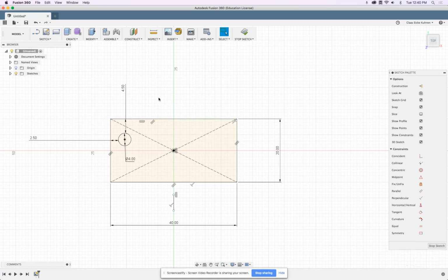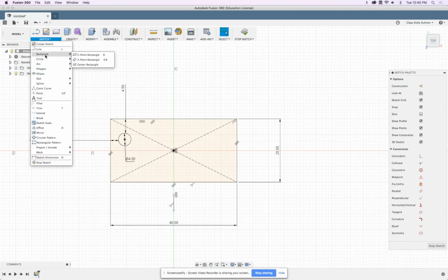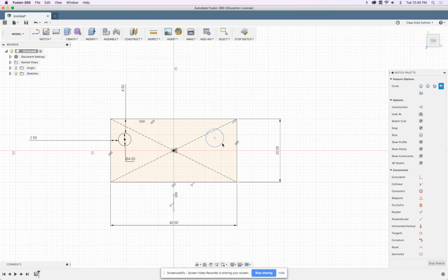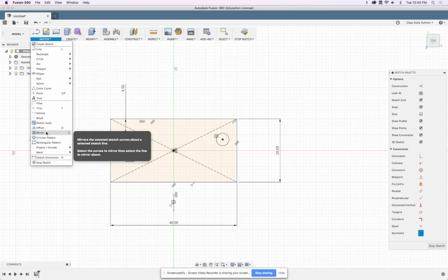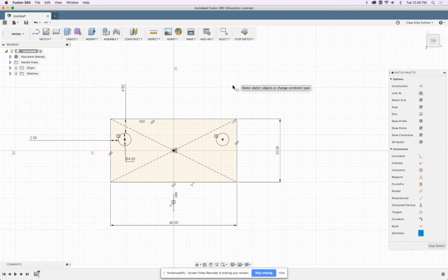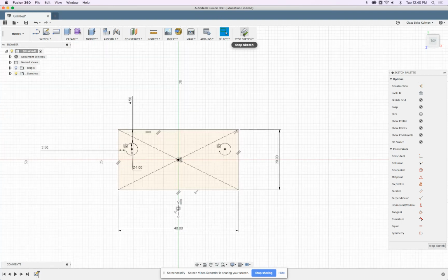A third way how to do this, including this line, is just make a circle. And then I say symmetry, use symmetry to this. And essentially, you see it's the same result as the mirror. And the mirror command does make a copy of this to there, and then it adds the symmetry constraints. So you see the symmetry is actually even faster. We just need to have this extra line. And to make sure this line is not confusing, we can just press X to make it a dashed line. Cool.